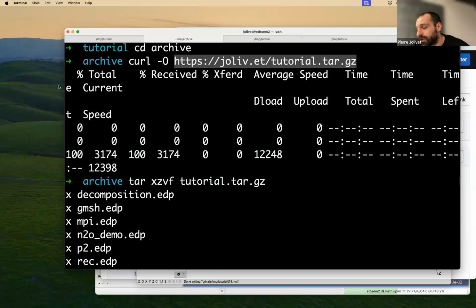So what's important when you think about nonlinear solvers in PETSc and FreeFEM in general, with its interface in FreeFEM, is that basically you need to provide callback functions, which either give you back a Jacobian or give you back the action of, the computation of some residual.